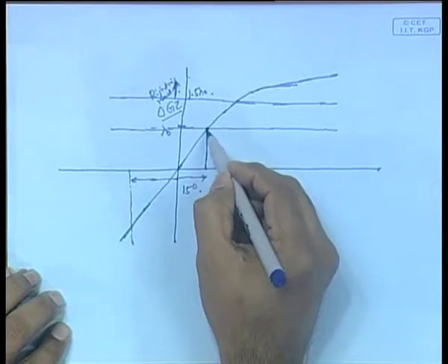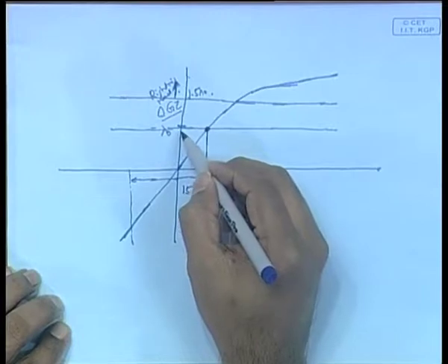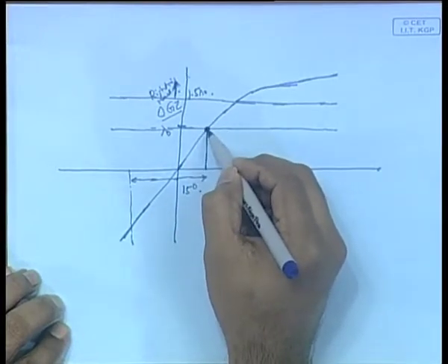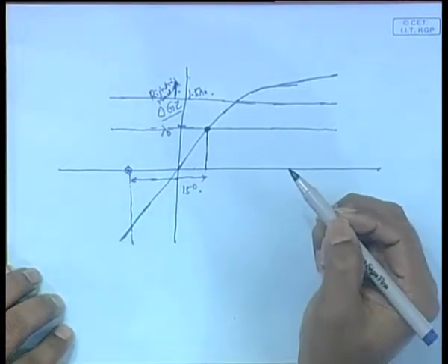That is the meaning of this term: we assume that the vessel has rolled 15 degrees into the wind. So, from its initial position, as it has assumed 15 degrees into the wind, it comes to this position. This position we know now, because we know lambda 0, we know the GZ curve. So, we know this position, we go 15 degrees back. This we assume to be the initial position of the ship. The ship is initially at this position, it heeled and came to this position because of the wind acting.